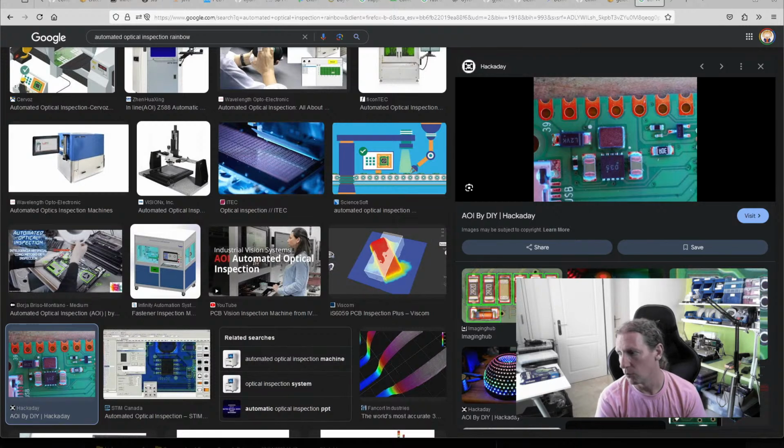Even if it's for just recording what the paste was like and then recording serial numbers of boards so that you can go, well, if I give this to someone, and that customer then has a problem with it, I can then go back to all the photos of all the manufacturing files that the pick and place machine did for every part that it put on the board and what it was like before it had parts put on the board and what it was like after. I want to be able to, for the customer, give me a serial number, and then I look at what I made and what I sent them so that I can say, send it back, it was a dodgy one.